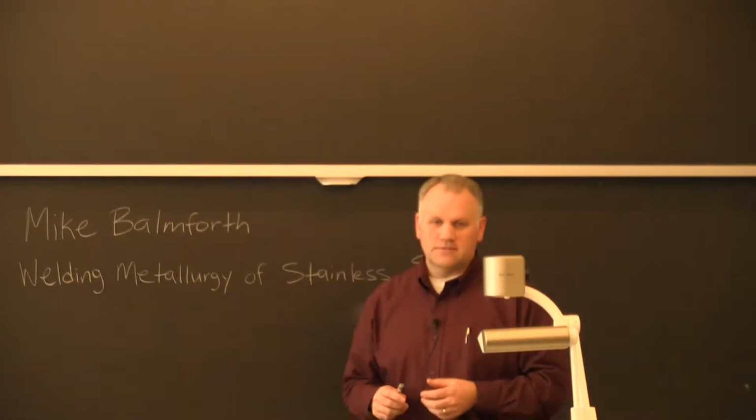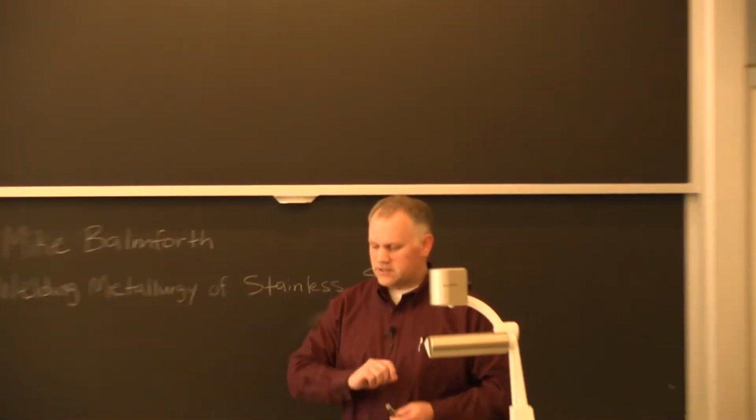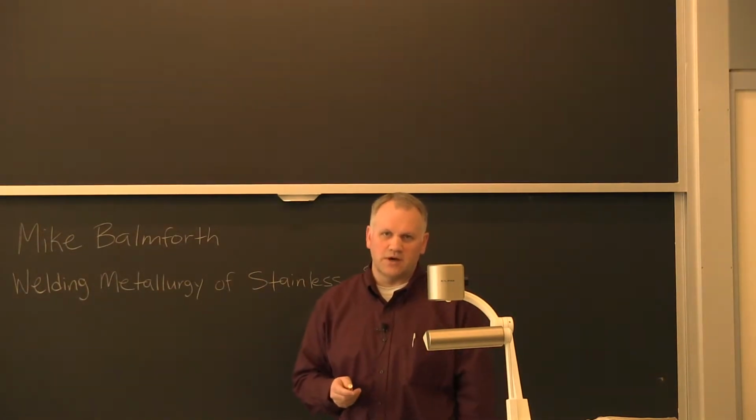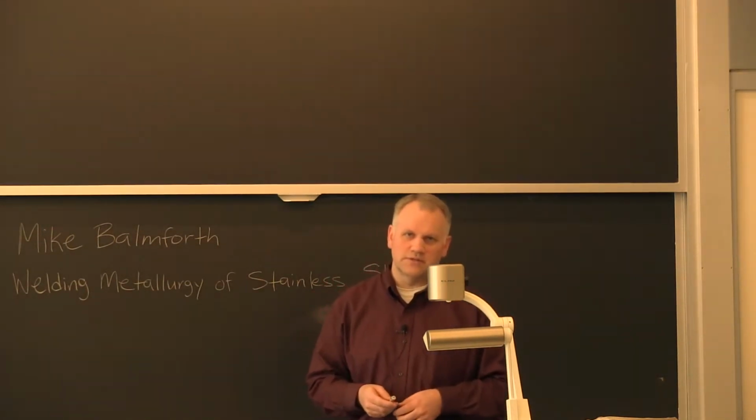When you're saying interpass temperature, that's the temperature between one pass and taking another pass, you're saying you want to try to keep it cool? Yeah. You want to keep it below 350, basically. So the way you do that is, maybe you make a pass. Maybe you have to wait a little while. If you just keep welding right on top of one another, you're going to get your temperatures up too high, and you're going to be more susceptible to corrosion.